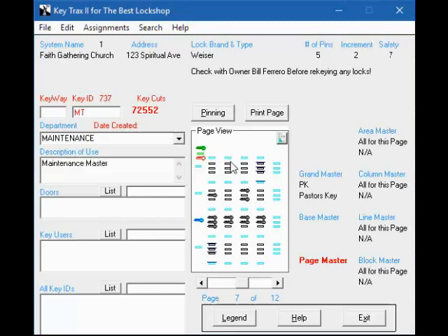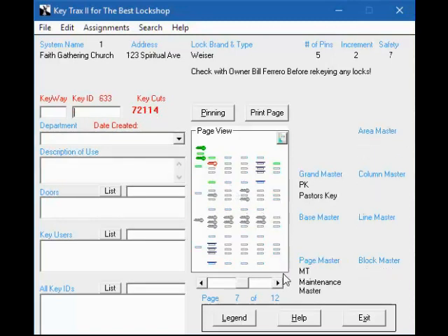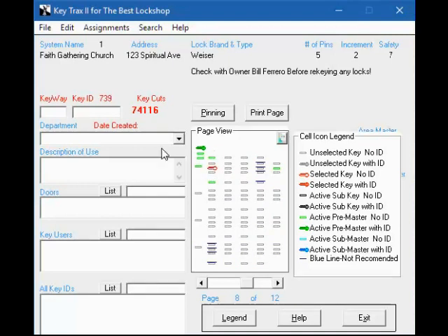Since we need to be able to rekey the house without affecting anyone but whoever uses the house, we will put that on page 8 using HS for that and key all the house locks to one key. As people leave, the house can be easily rekeyed and a new key issued. The rest of the church will be on page 6. Here we will put the pastor's office, PO, the assistant pastor's office, AP, and the secretary's office, SO.